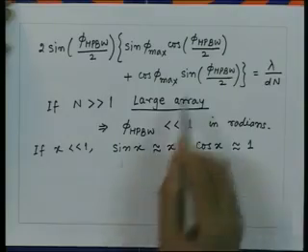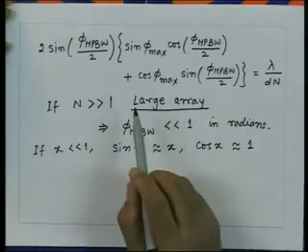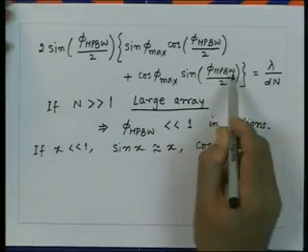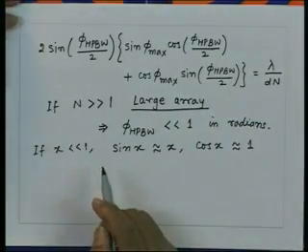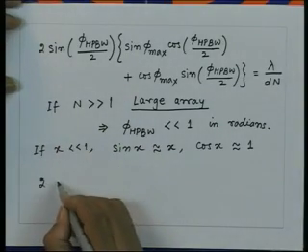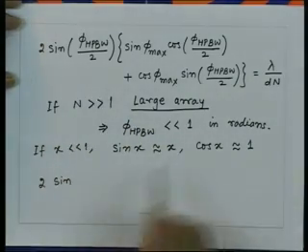So, I can substitute now into this. This quantity here is very small, so I can make this quantity almost equal to 1, and this quantity is half power beam width divided by 2. So, we can write down this expression now approximately as 2 times sine of, well, we are approximating this also by x.